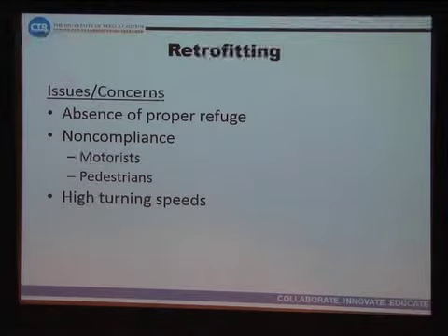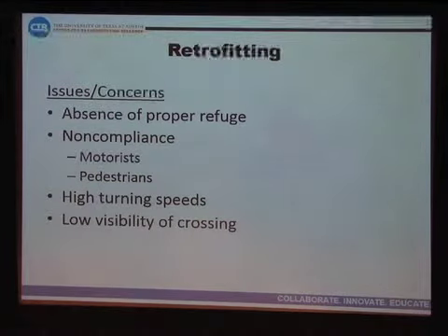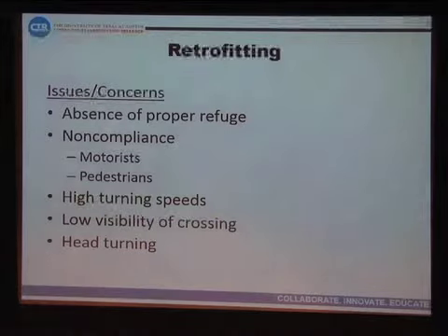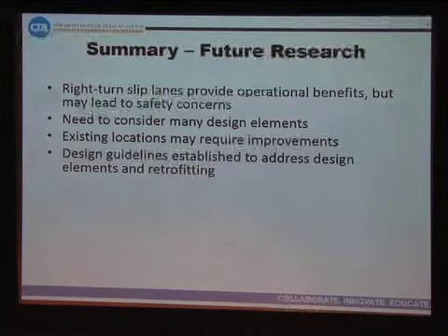We looked at mitigation measures for excessive or high turning speeds, as well as low visibility of the crossing location itself, and then excessive head turning on behalf of the motorists as they look for gaps in oncoming traffic. We developed treatments for these issues that are consistent with those provided as recommendations for new construction.